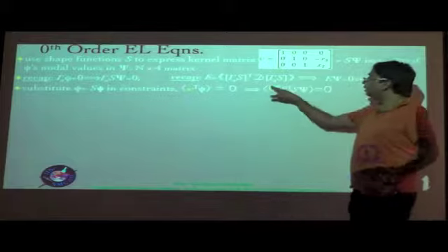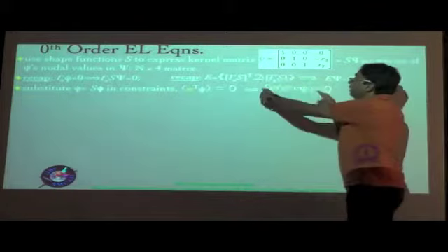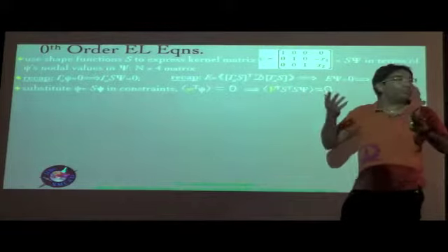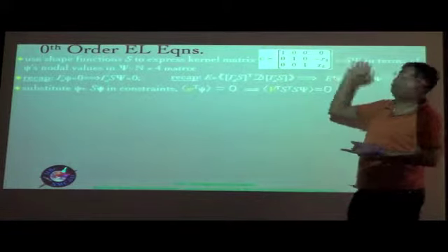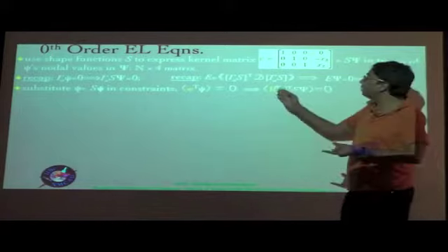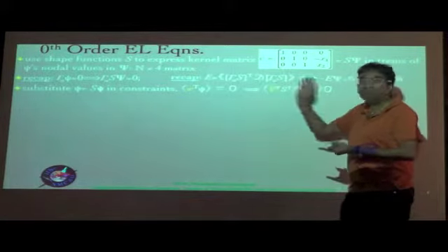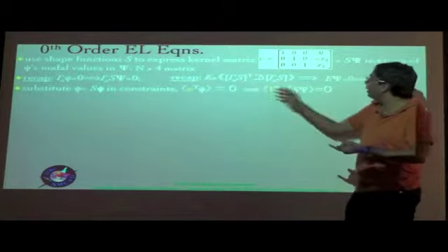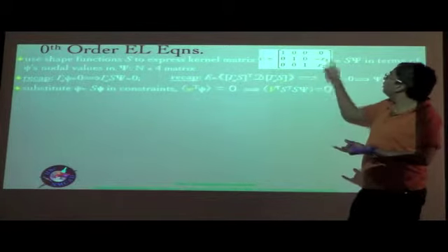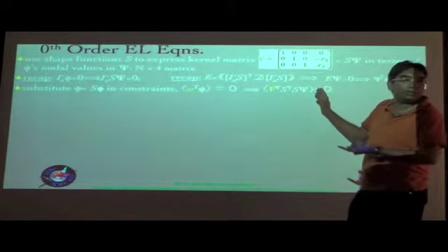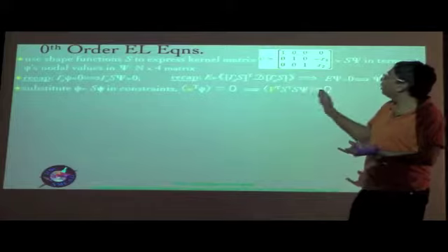Now if you look at this, the integral is over the cross-sectional coordinates x2 and x3. V is not a function of x2 and x3 because the actual values of x2 and x3 are already substituted into it. It's just a numerical thing, the unknown quantities, the amplitudes of the warping. So that comes out. And this xi, which is the numerical values of x2 and x3, is also a constant with respect to x2 and x3, and therefore it also comes out.